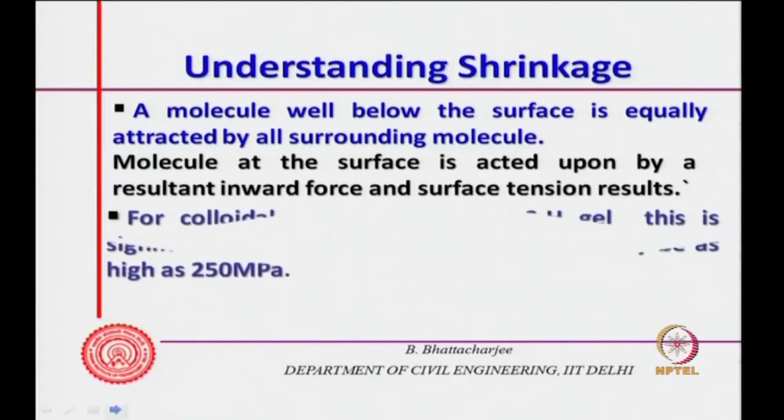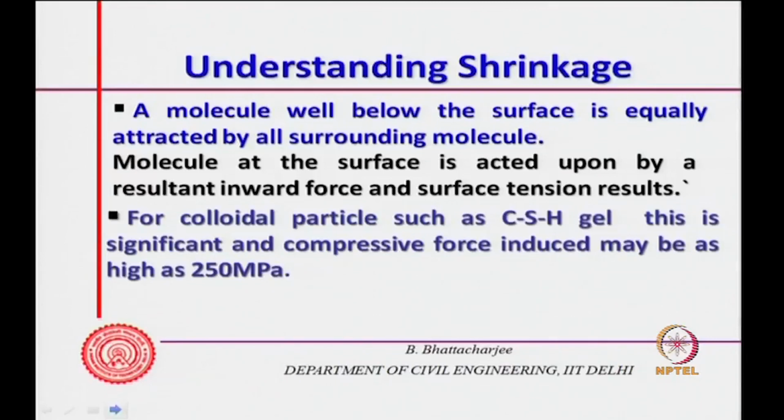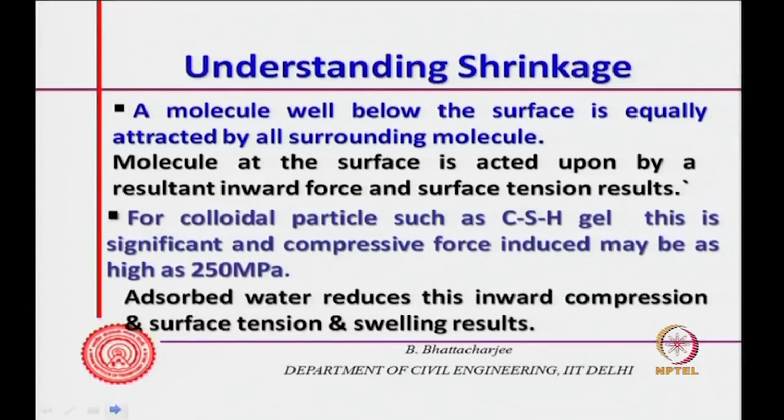For colloidal particles such as the CSH gel, this is significant, and the compressive force induced could be as high as 250 MPa. So, if it is dry, there is a compressive force acting downward into the skeleton. Now, I bring in adsorbed water, which reduces this inward compression and surface tension, and swelling results. In other words, the surface tension of the CSH system has reduced, so swelling will result.